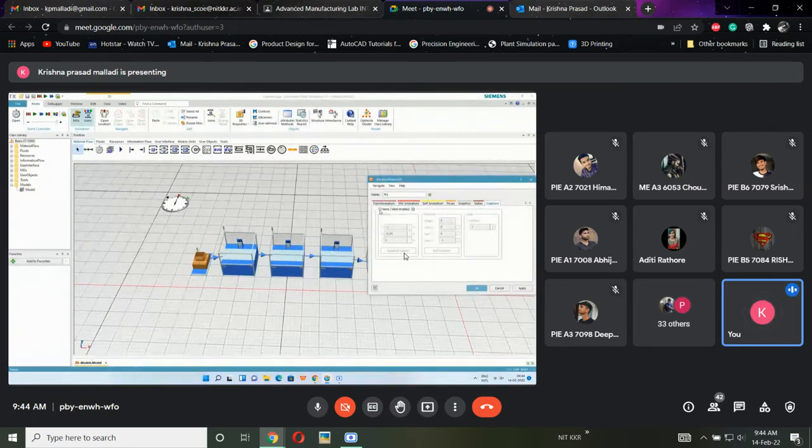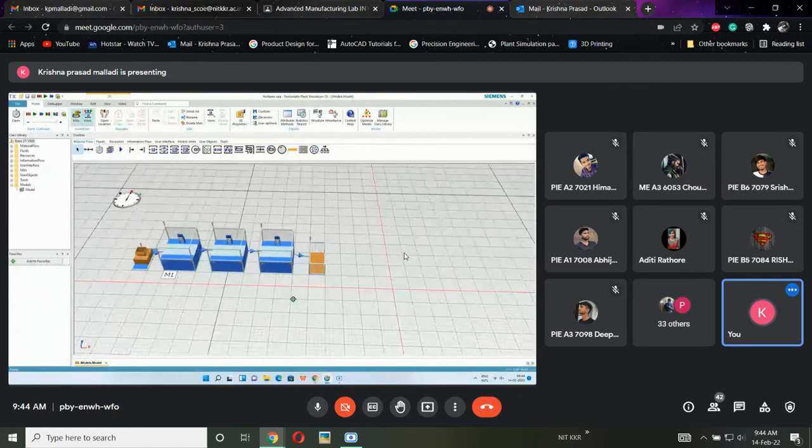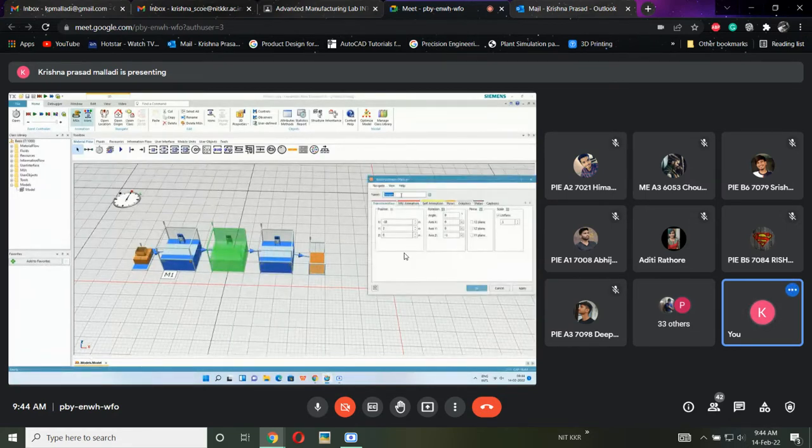In this, there is a name or label option. You need to enable this one. Same, right click, edit 3D properties. Here it is station. Okay, I want to use the same name. So station, and if I want to enable the name here, then I need to enter into captions, and here I need to click on this one, name. Then it will be enabled.